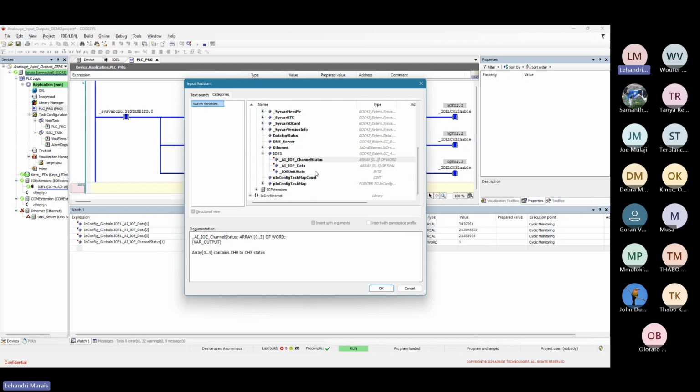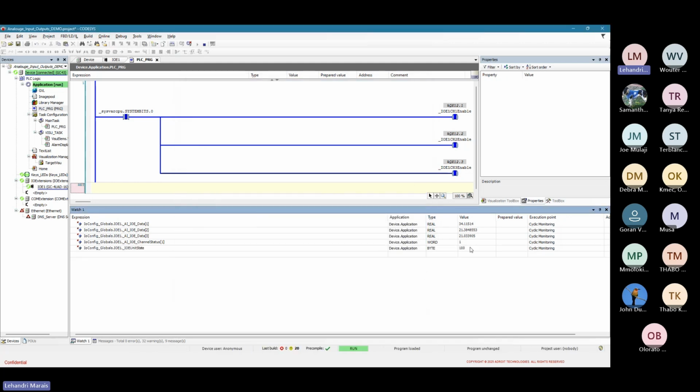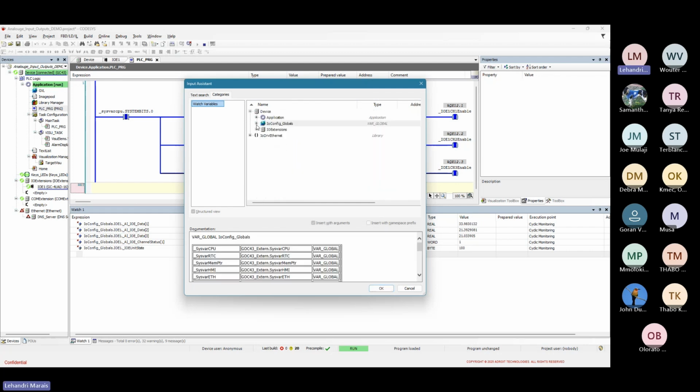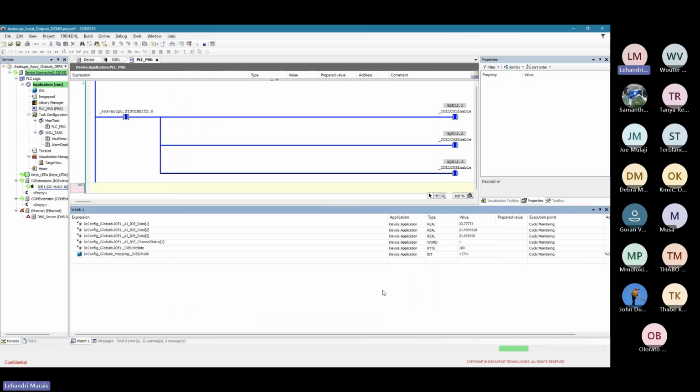And last but not least, unit state, it should reflect 100 because the unit configuration reflects what is on my GOC and the unit is in a running state. Now, checking the IO variables right here. If I go to the channel 1 OK, it should be on because it shows that my channel 1 is enabled.